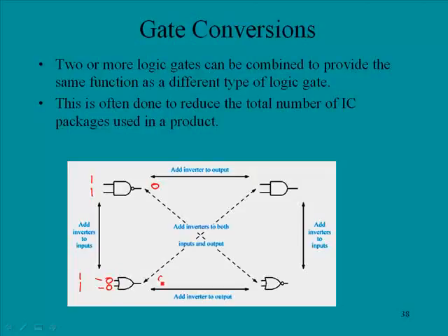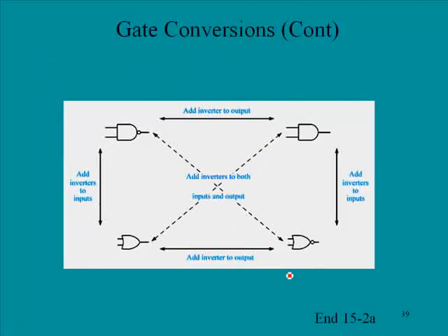so we would have a 0 out. Let's try one more. If we had a 1 and a 0 going in here, then the AND gate would produce a 0, but it would be inverted, so we would get a 1. So let's try that in this one as well. If we had a 1 and a 0 going in here, then we would get a 1 out, so that would satisfy that one. So those two could be interchangeable, and the same thing would happen with these two. Let's jump to the next page and we'll look at going across.